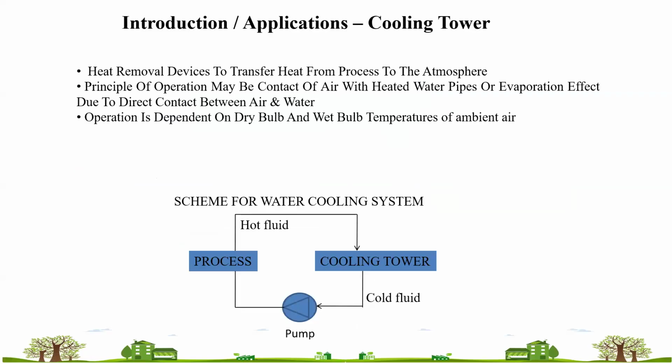That is a stricter, or we can say more critical, thing in your cooling tower performance. If you are not providing enough ambient air, for example placing a cooling tower in an enclosed area or covering it with other mediums, like I have seen multiple examples where people have barricaded the cooling tower with green shade.